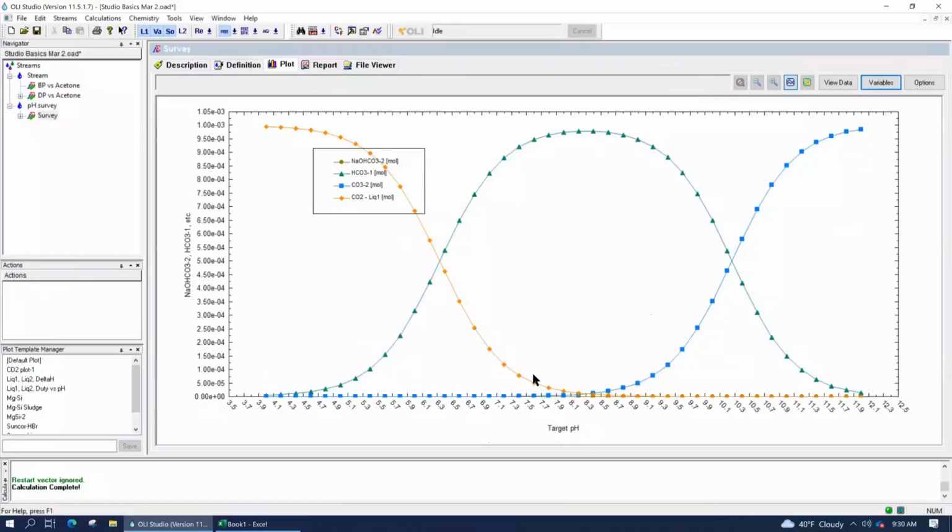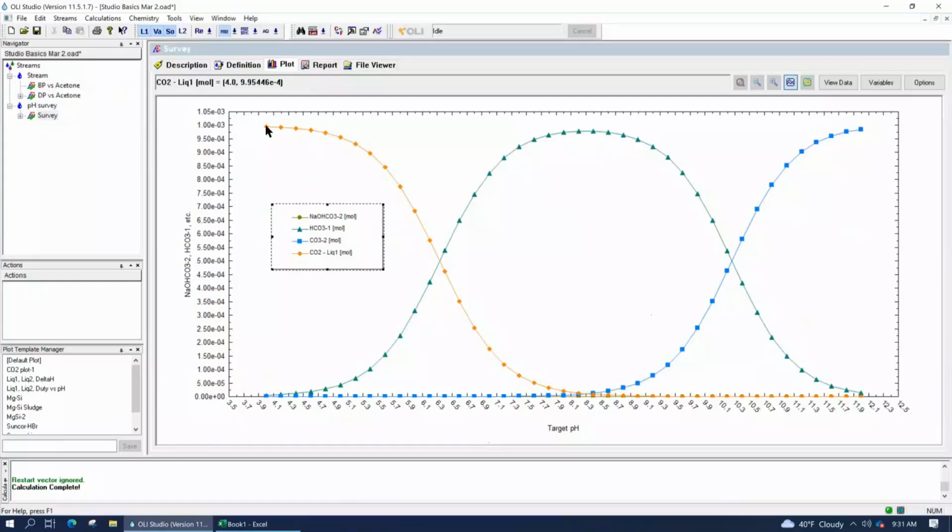Okay, it's a nice symmetric plot. And the cool thing about this, especially from a water chemistry standpoint, is that this is a typical plot of what we call a diprotic acid. That means CO2 can give up 2 hydrogen ions. The CO2 essentially, when it reacts with water, forms carbonic acid, H2CO3. From that point of view, H2CO3, you can see those 2 hydrogen ions are given up at different pHs. So here, for example, where we have essentially molecular CO2, that's the equivalent of having carbonic acid, free carbonic acid.